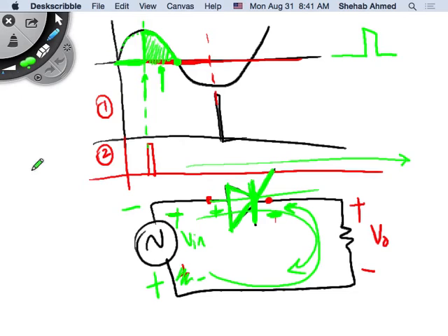I can keep the voltage across the capacitor, but is it going to consume current? The MOSFET's gate looks like maybe a small R and a big C here. If I've charged my gate capacitance, it will remain charged. There will not be a continuous current being sucked from my gate power supply, right? So that's why it's called a voltage control device, not a current one. As soon as the voltage across the gate capacitance reaches a certain threshold, that is enough to turn on the device. You don't need to maintain current in the gate. That's why people like MOSFETs. They really like MOSFETs because of that.